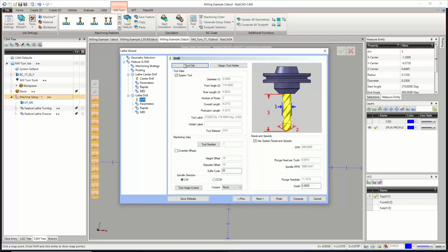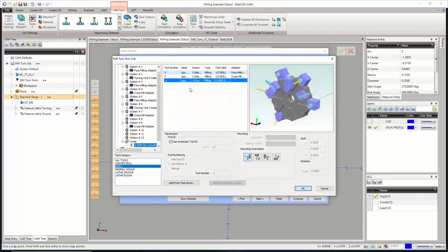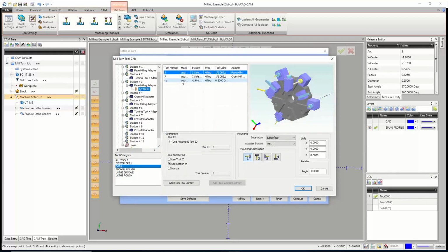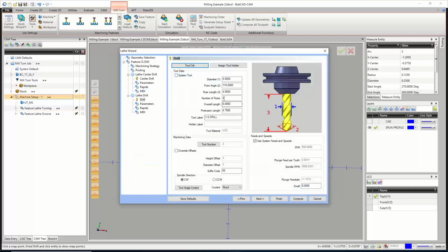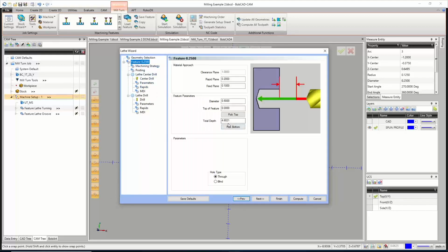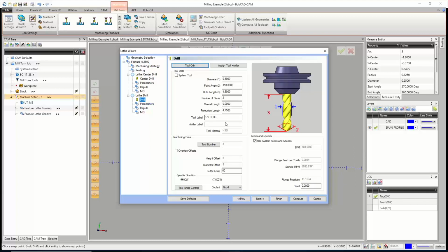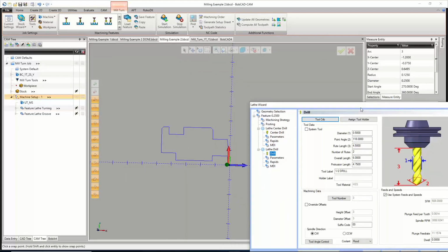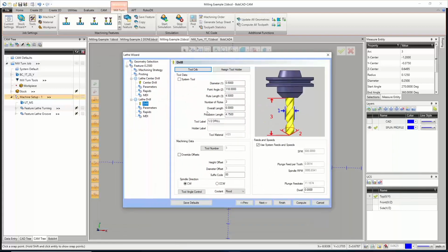And then for the drill, once again, I'm going to pick our drill as the face milling drill and hit OK. I think it could be the depth that we're going. What's the depth on the hole? 4.6. And the stick out on our drill is 4.75. So it's close. We don't have to drill that deep either. Because technically, we really could clear through back there and then clean up the rest from the other side.